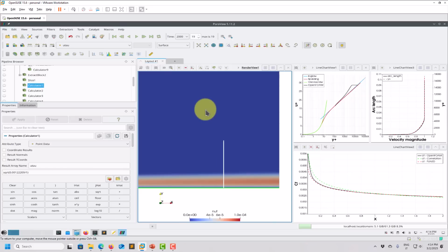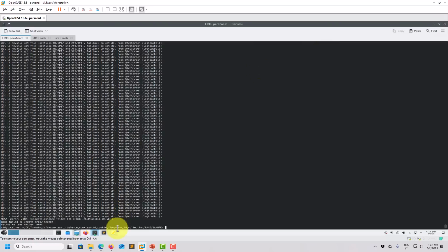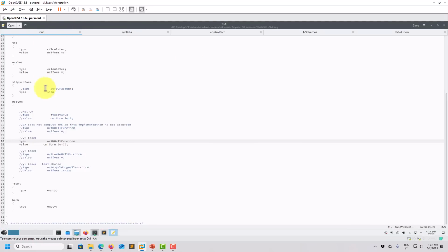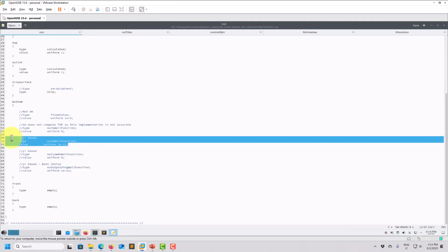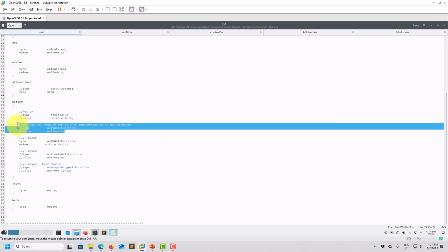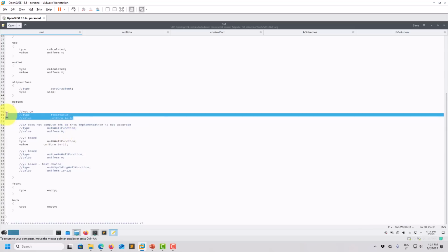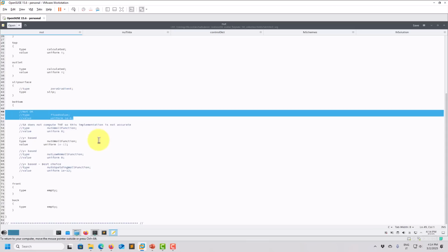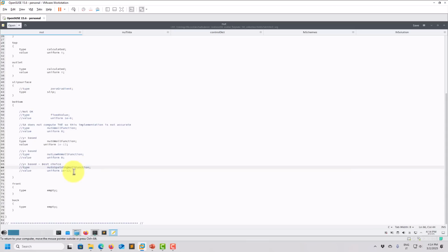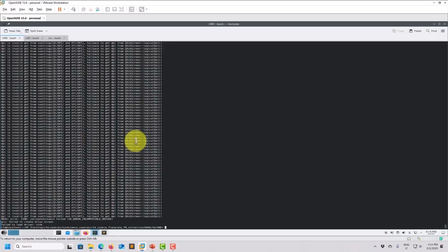So this is how we set the Spalart-Allmaras high rate. Okay, so we validated. Important takeaway is that for high rate, I recommend you to go for this one. This one you can run in the next video. We're going to see differences and what is happening, but the results are wrong. You can even disable everything, taking that DNS approach and so on, but the results are not going to be correct just because of the mesh and so on. So let me close here. We're done with this case, and now let's move to the low rate.